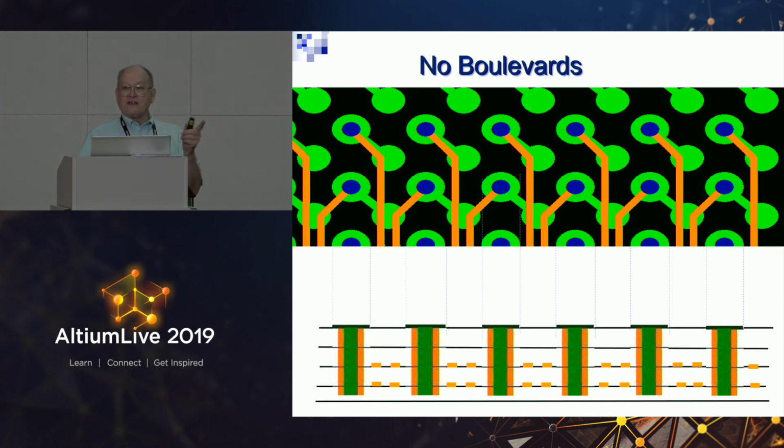So the holes are not only in the way, but the holes are transmitting noise, because I'll show you some graphs. Once there's a signal that has a lot of noise on it next to a through hole, it capacitively couples over, goes down the through hole, and then contaminates every single signal next to it on other layers. So through holes are really, really bad. You need to get rid of them.